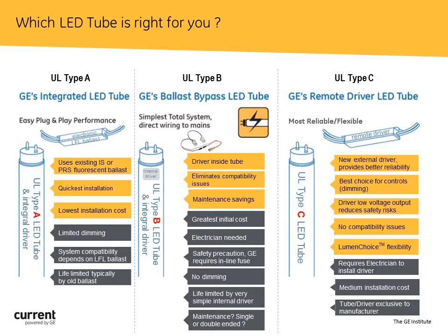What are the negatives on Type C? First one we've already mentioned, requires an electrician, but that electrician is going to be pretty good at this because he's taking out the old ballast and then she's putting in a brand new LED driver, which by the way is exactly the same size. All the wires are there. You simply remove it, you splice in the new wires, put in the new tube, and boom. Medium installation cost.